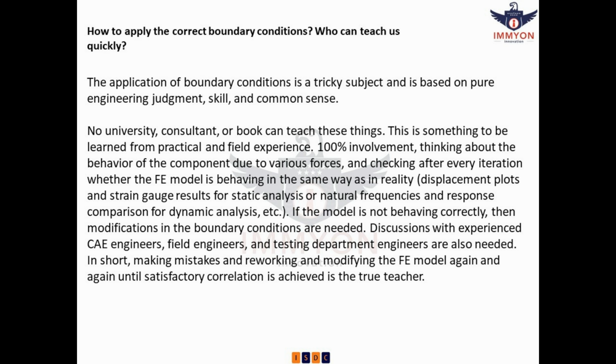It requires 100% involvement, thinking about the behavior of the component due to various forces, and checking after every iteration whether the FE model is behaving in the same way as in reality: displacement plots and strain gauge results for static analysis, or natural frequencies and response comparison for dynamic analysis, etc. If the model is not behaving correctly, then modifications in the boundary conditions are needed.